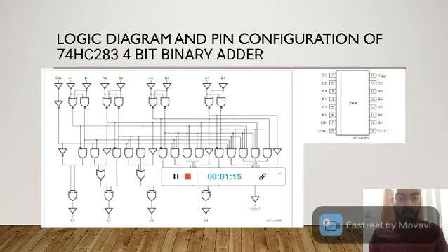In case of all active low operands, the result S1 to S4 and Cout should be interpreted also as active low. With active high inputs, CIN must be held low where no carry is intended. Interchanging inputs of equal weights does not affect the operation. The CIN, A1, B1 can be assigned arbitrarily to pins 5, 6, 7, etc.